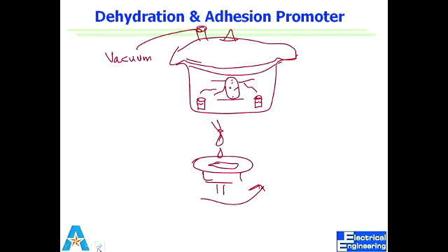Either we can spin coat it, which would be the same way as before doing resist, or what we do is we have a vacuum chamber, a small enclosure where we can put small containers which have HMDS in them, and place a wafer in the middle, close the top, suck the air out, and leave the wafer in those vapors of HMDS for some time, right?